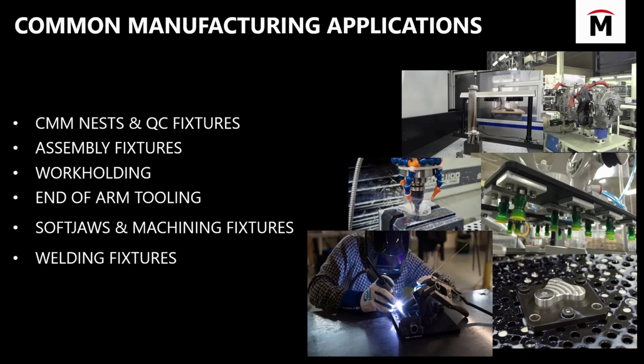So let's say, the picture there on the bottom right actually shows it great, where that particular part got machined on one side and then it had to be flipped over and bolted down for the secondary machining. So it holds that part extremely tight while we do a finish machine on it.